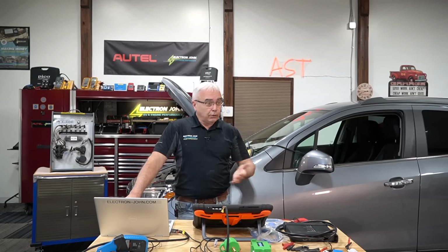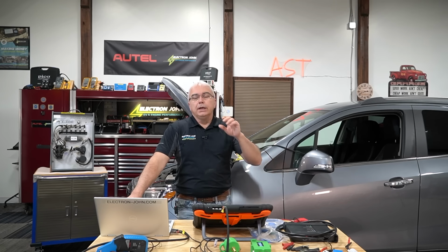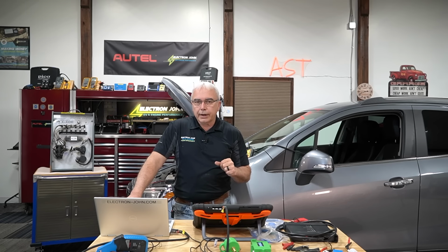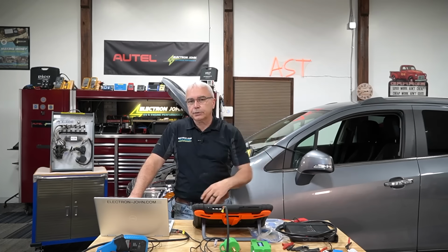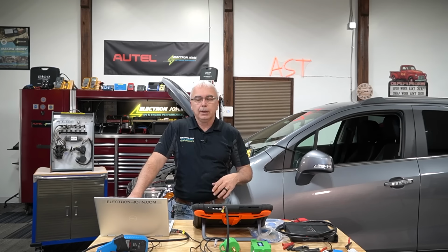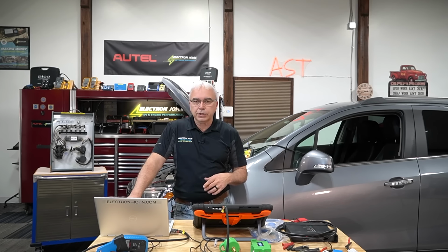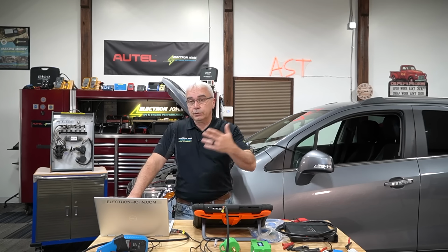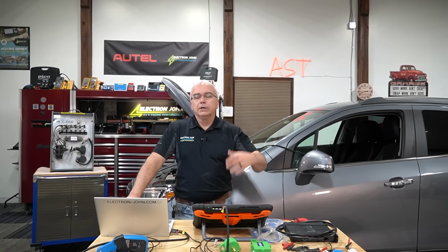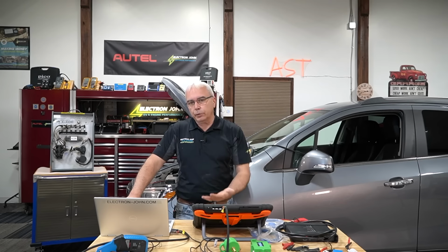I could do those old-fashioned mechanical types of tests. Maybe I open the hood on the car and I say, hey, I want to do a compression test, but half the cylinders are covered by an intake manifold, but I still want to know if I got good compression. Well, maybe I do a relative compression test, right? As opposed to a mechanical compression test. So I have a lot of options available to me.